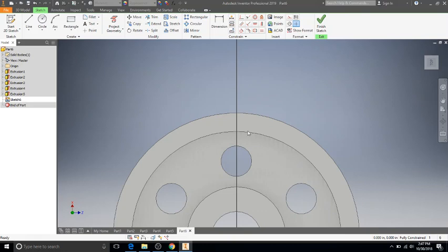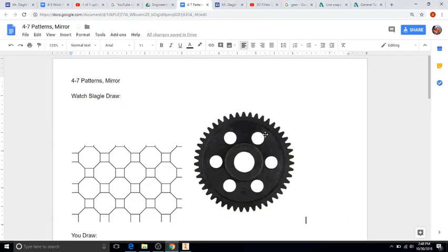We already kind of did the math there for what we needed to do, and we just created a circle and copied it 6 times. We didn't really do much that was interesting. Well, now we got a problem, because if we choose the wrong size for our teeth and we copy, they might run into each other. So we got to do a little math and think about how wide each of those gears and each gap takes up. So there are 47 gears, which means there are 47 gaps between gears.